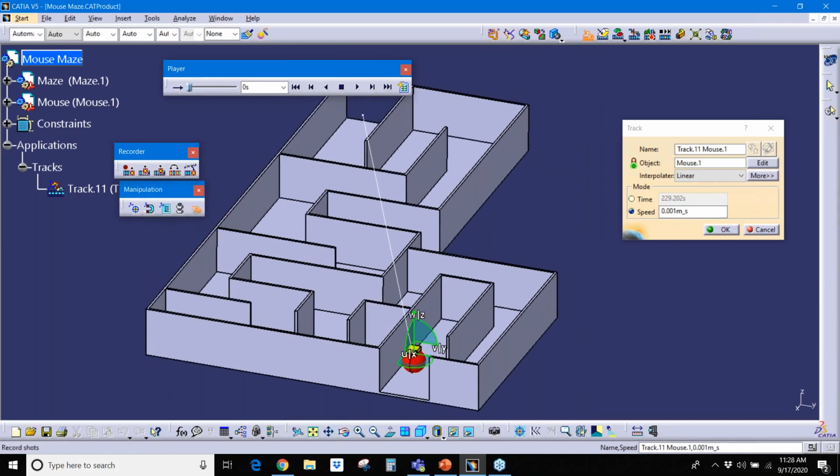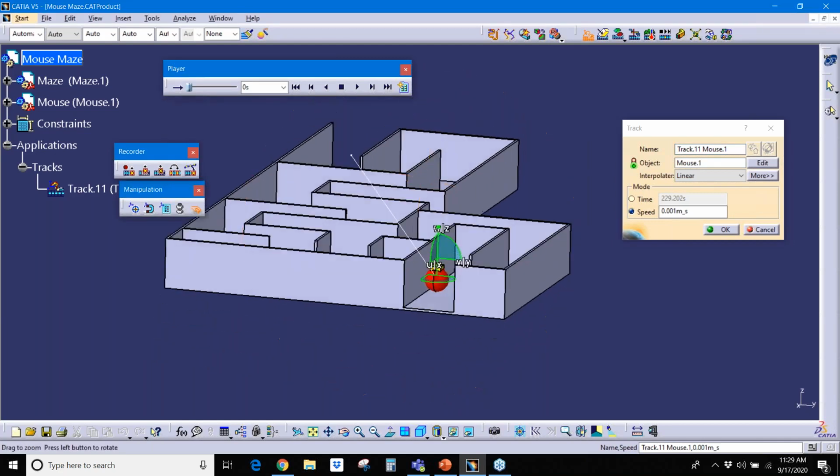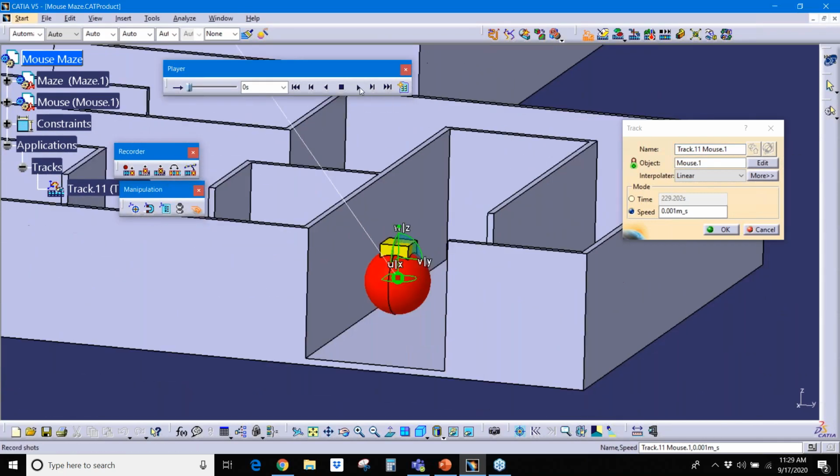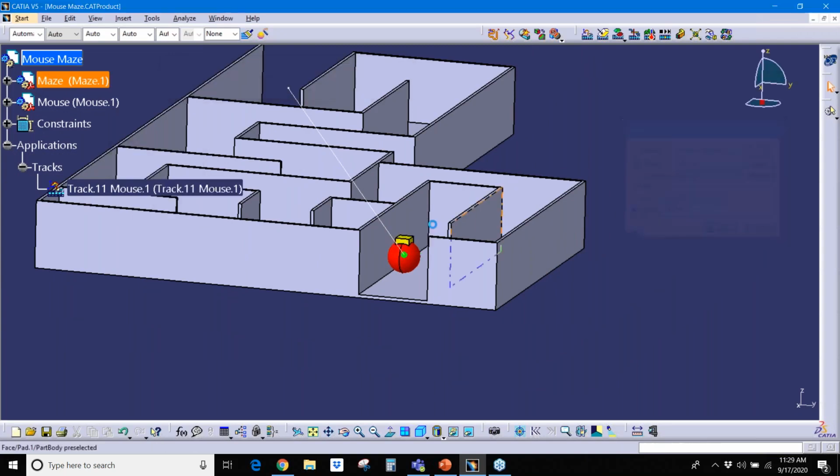It's always on you guys to do your due diligence and make sure there's no clash. But here is a button. These are what we call our clash detection. You can turn the clash detection on to stop the simulation dead in its tracks if it detects a clash. So let me zoom in here and replay it. As soon as it hits this very first wall, it stops at 12 seconds. It says it can't go any further because it knows that it hit that solid object. So let me rewind this to the beginning and click OK.